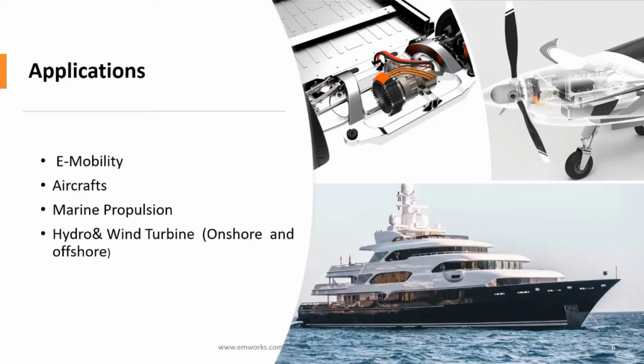They can be used also as a generator for the high frequency systems of ships and aircraft, since they can have a high number of poles with a compact structure. In addition to those, water and wind turbines use the axial flux machines due to their high efficiency and low maintenance costs. An axial flux generator used for wind turbines can reach an efficiency of 96%.